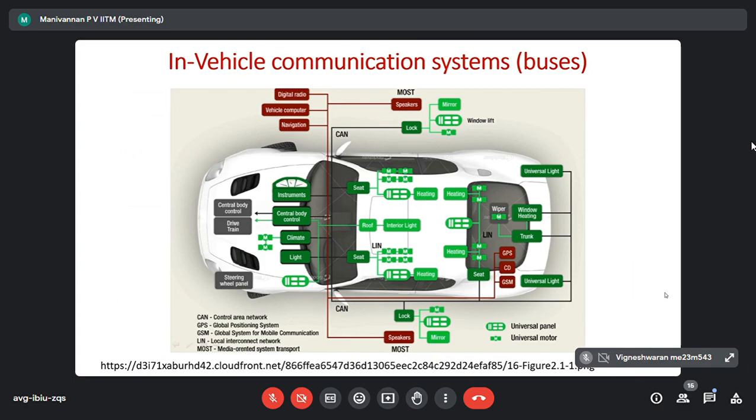They need to talk with each other because, as I told you, when you apply a brake, the fuel injection should be reduced. So automatically the ABS ECU will send a command requesting, because ABS cannot control the engine. The engine is controlled by the engine ECU only. So the ABS will request the engine ECU, please reduce, I am going to apply brake. Correct? The message may be continuously updated. Similarly, each of them needs data sharing. So for that only we need communication systems or communication buses.